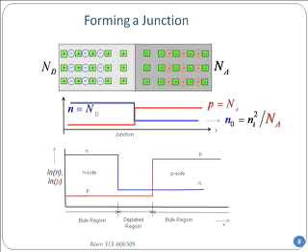Now, this is not really how it happens. What happens is that it will not drop down all of a sudden, from a fixed value to zero. That's not going to happen. Actually, it drops down very gently. And similarly, for the holes, it drops down gradually from one side to the other as the potential has built up. But this approximation where I have sort of approximated with a sharp drop is called the depletion approximation.